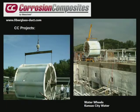Let's go on to the next one. Here you're looking at another unusual project. This is the city of Kansas City. And they had first designed these wheels, we call them water wheels. And what they do is, if you look down in the lower right, you'll see some big wooden paddles. These paddles mix the flocculant into the water coming into the plant. The flocculant is mixed with the water to drop out all the particulate before the water goes to the clarifiers. It's a common practice in water plants.